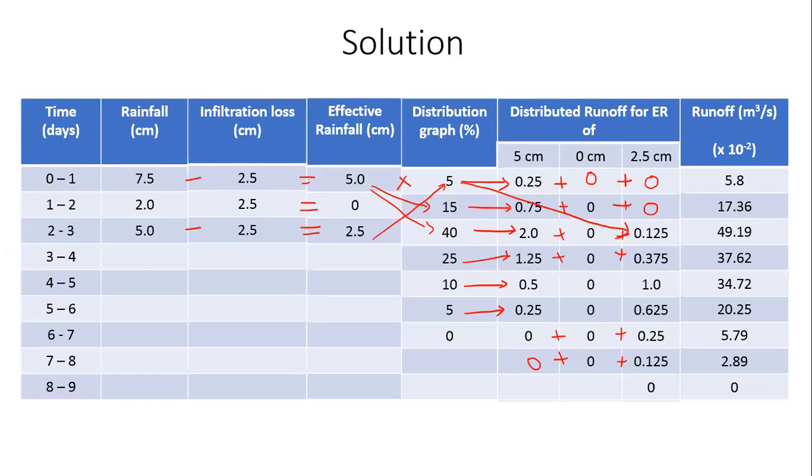See, the thing is this: the 2 centimeters of rainfall that happens on the second day is not even enough to account for the infiltration losses, interception, all of those losses. We are just incorporating that into the phi index. So imagine this: I receive a major rainfall event, and runoff starts to happen. The runoff will take its own duration, whatever it may be, 5 days, 6 days. The next day, I receive a little bit of rainfall.